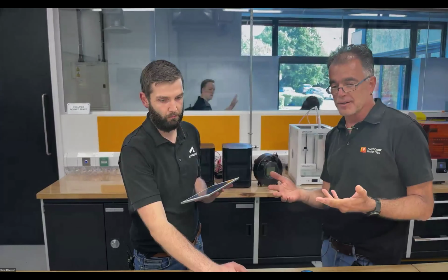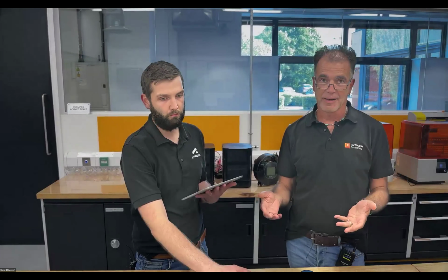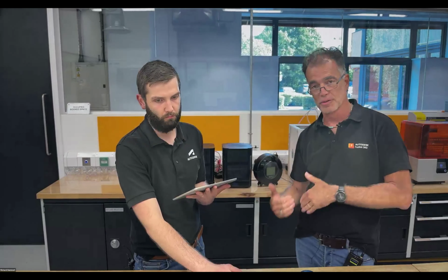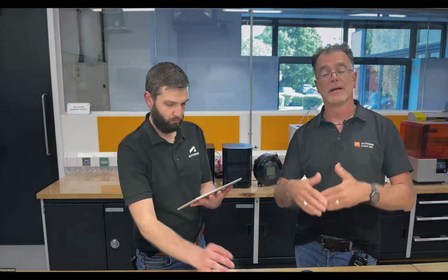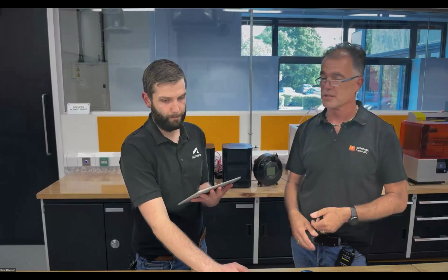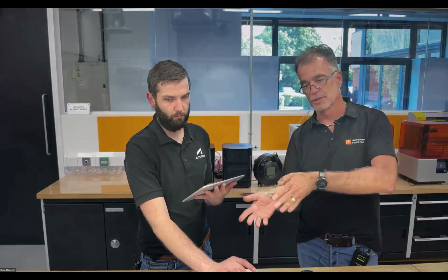So yeah, actually, you see, if you start Fusion, you get the mechanical workspace. So there is a setting in the preferences where you can switch and you can get automatically into the electronics design workspace. If you don't have it for the first time, you have to go into the file menu and then you say, okay, new electronics design. And then that's the place to start, where you can start with a schematic, go into the 2D PCB, add components to the PCB and so on.